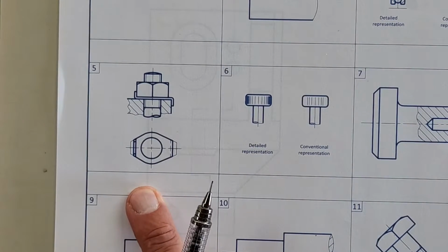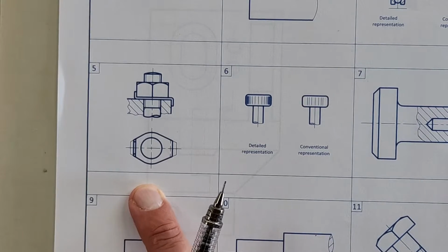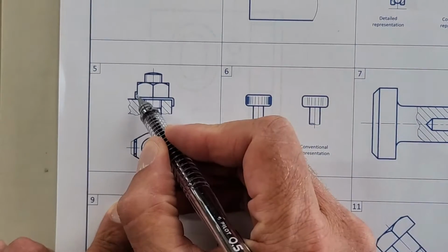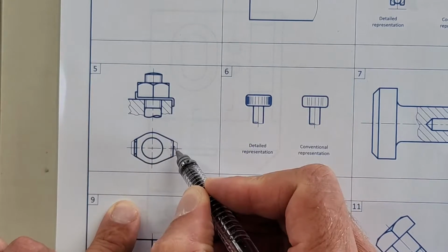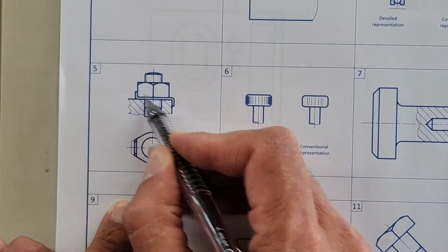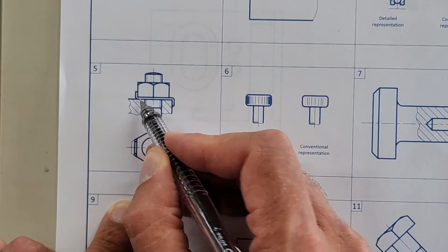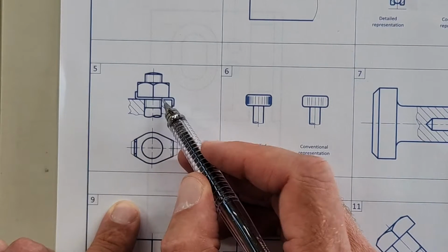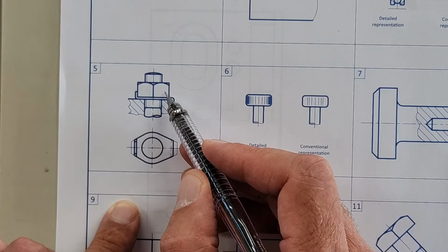All right. Then on number 5, that's a locking plate, sluitplaat in Afrikaans. So what you can see here, it's a flat plate. The one side folds around this corner, the other one folds around the side of that nut. And if this nut isn't tied into that spot, there's no way for that to come loose. Locking plate, sluitplaat in Afrikaans.